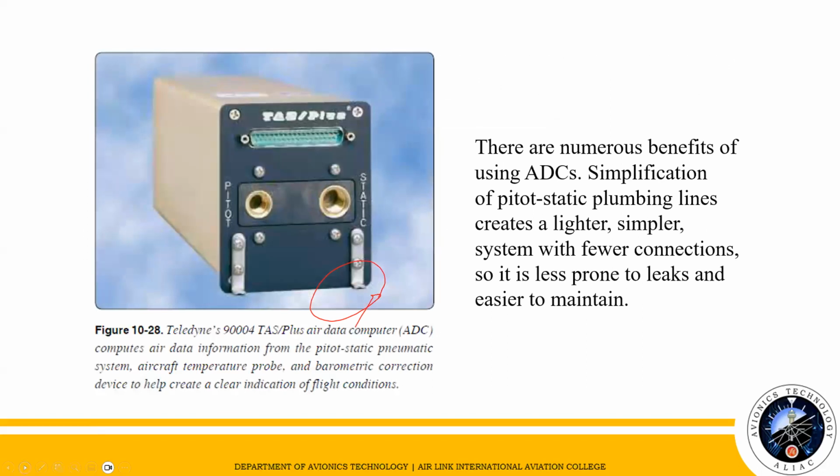So, merong mga numerous benefits paggamit ng ADC. Siyempre, unang-una doon yung simplification ng pitot-static plumbing lines. Create a lighter, simpler system with fewer connection. So, mas lesser siya sa prone to leaks and easier to maintain.